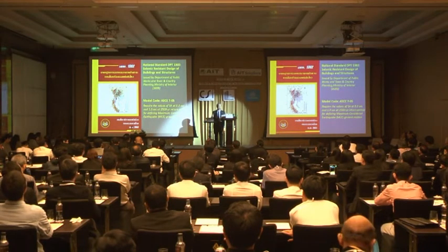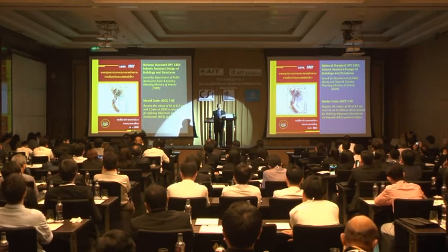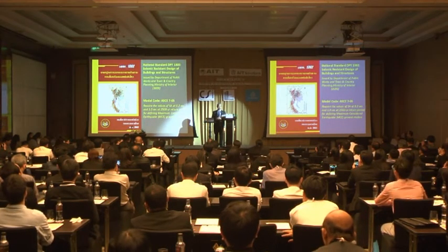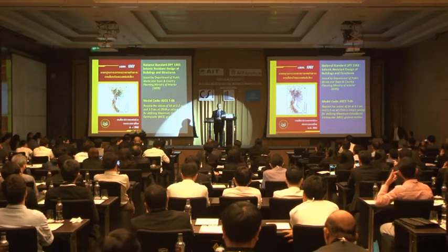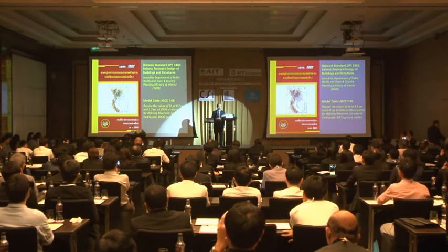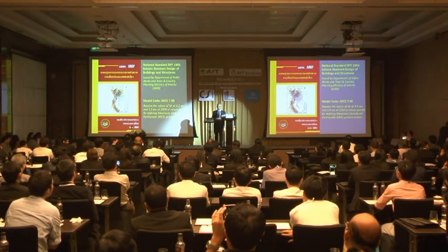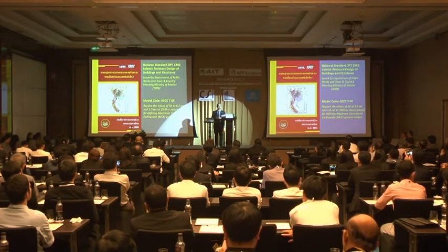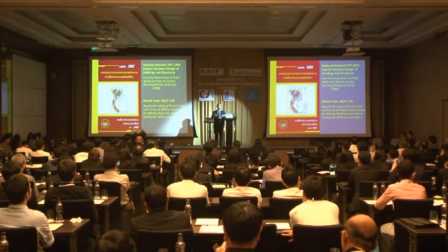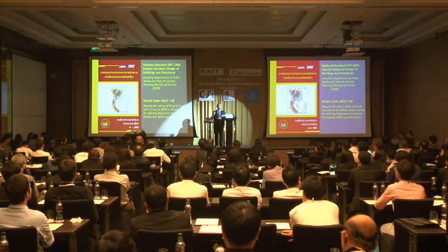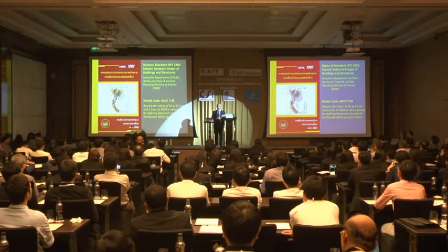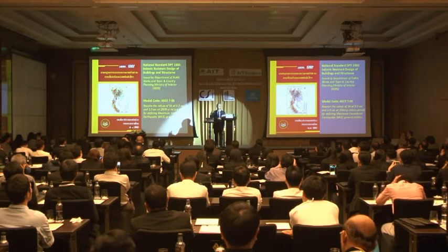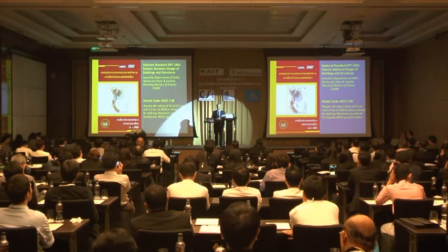national seismic design standard. So this is our national seismic design standard, incorporating a new seismic hazard map integrated into our seismic code. We use the US code as a model, but we use our own hazard map to replace the ground motion parameter in the US. So we can design our building and structure to be compatible with the safety level as those in the US. That's the idea.